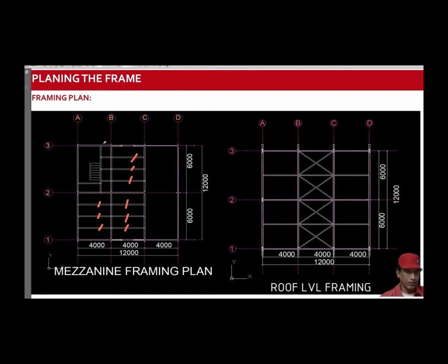These are also main beams, but these are simply supported main beams. It helps to transfer load similar to the joist while it transfers the gravity load, but its behavior changes when it transfers the lateral loads.